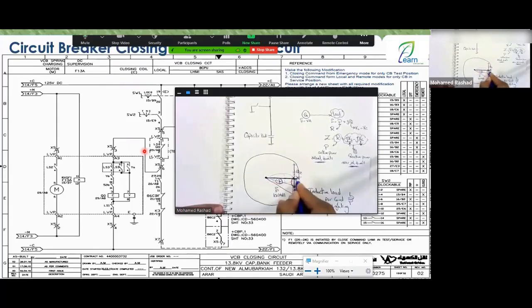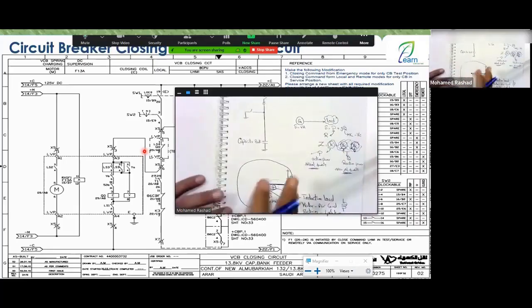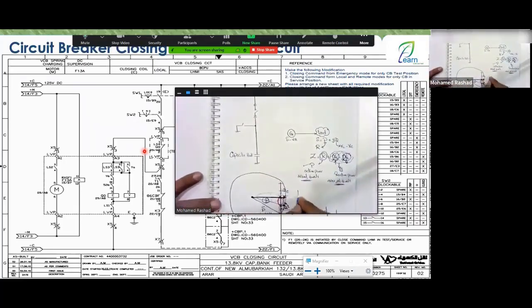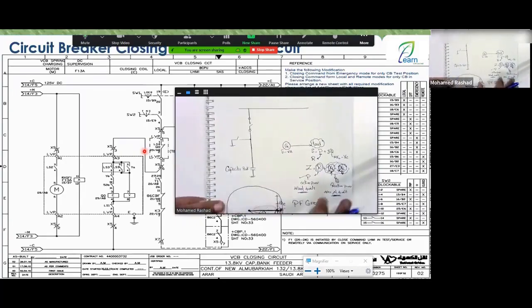It's converted to power. So if I reach a point where the capacitive reactance equals the inductive reactance, these two cancel each other out, leaving me with just this, and I have obtained additional power. This is the goal of the power factor correction concept, which is improving what? Improving the power factor, right? Very good. Well, I don't want just that. I am not introducing the capacitor bank just to achieve power factor improvement. So what else do you want, Engineer Rashad?